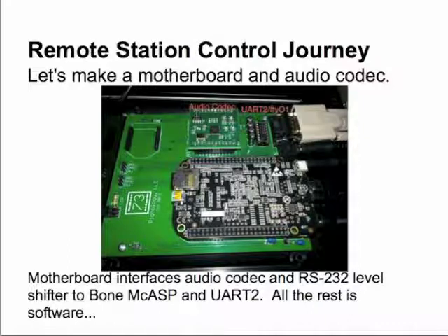It's about 1.5 inches square, and it has a 1.8 volt voltage regulator here. There's an oscillator, and then this is the actual codec, which is a Texas Instruments audio codec, and then the other passive components to bring it down to the headphone jacks right here, which are 2 stereo 3.5mm headphone jacks.